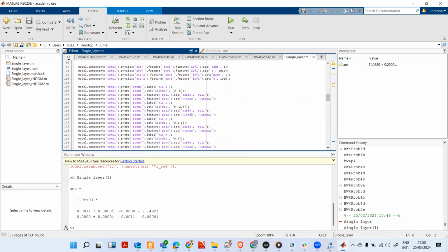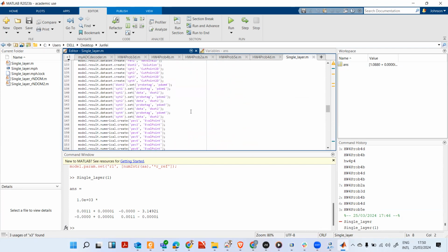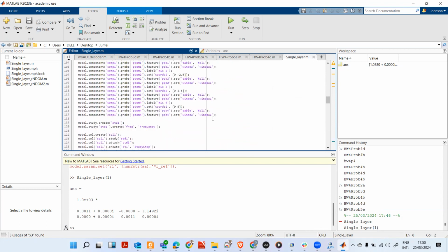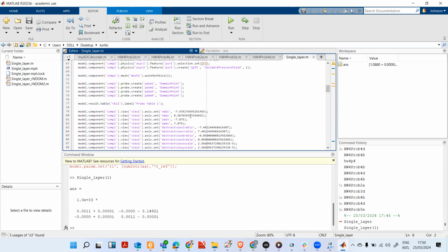And with that, there are a lot of things to play with, right? For example, in some of the pretty complicated models I've created before, I have like 200, 300 boundary conditions I want to control. I cannot just put them in by hand. That would be a lot of errors. So what I did is I create the COMSOL file in the most general case, and then select the boundaries by calculating their coordinates, so that I can always use for loops.